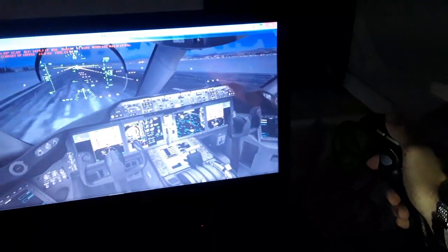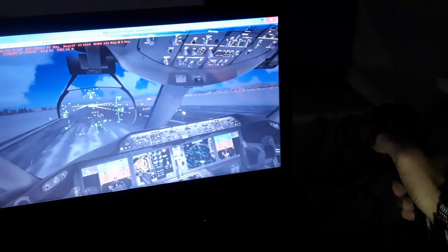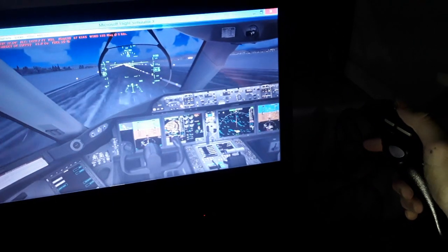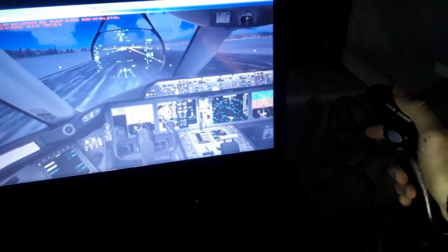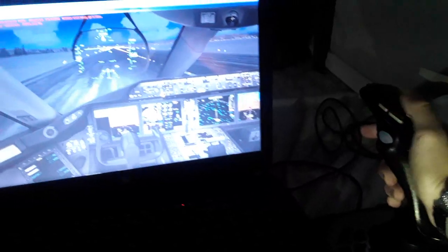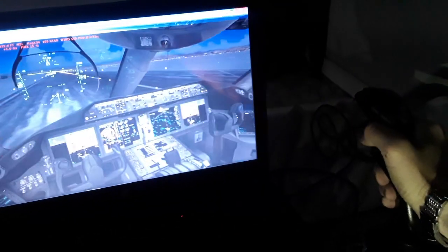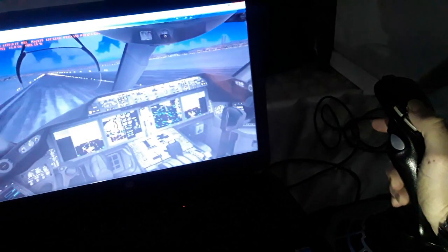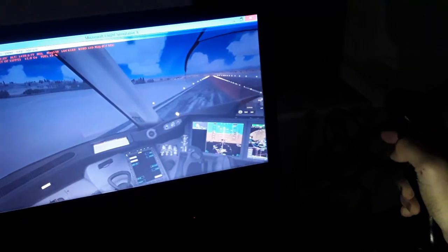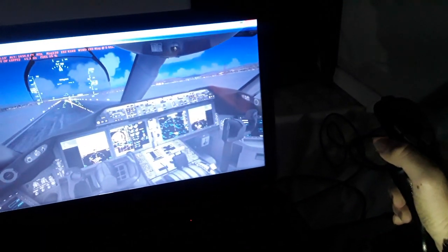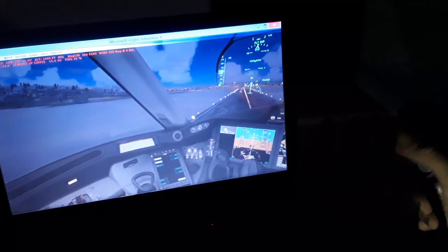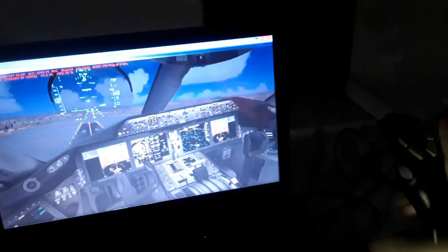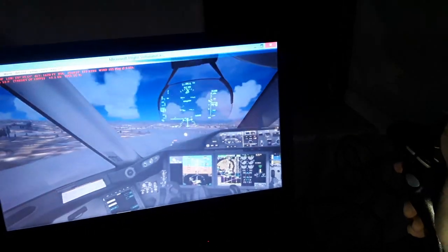So we hold the yoke down to pressurize the nose wheel and use the rudder for alignment. Rudder pedal left. We have 80 knots, 100, 120, V1 over here, 130. We rotate. So we rotate 9 degrees or less, pitch attitude for takeoff. So we have the maximum takeoff power over here.